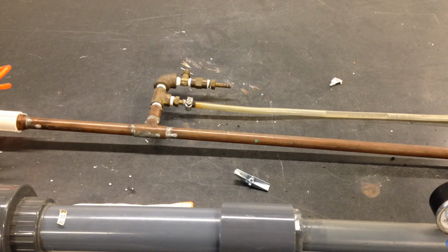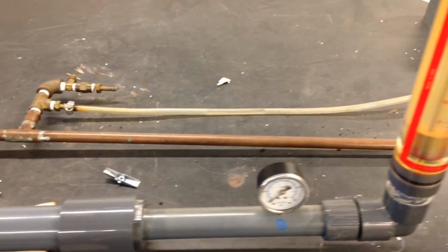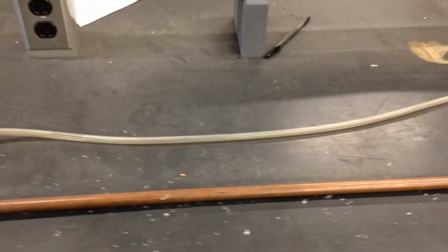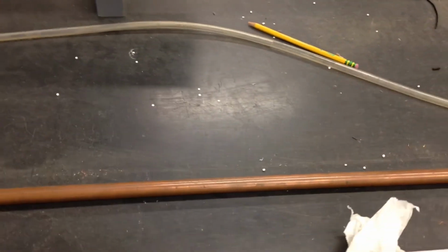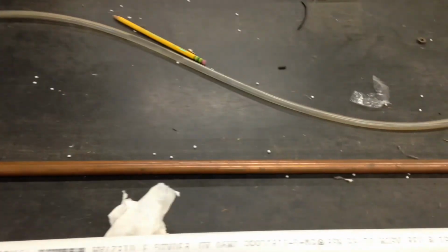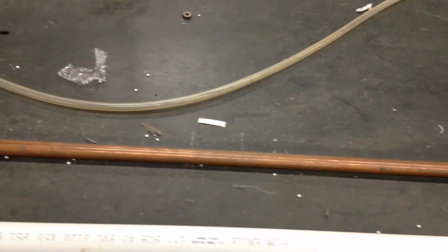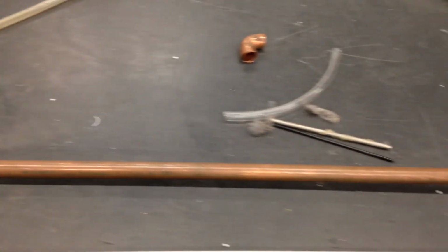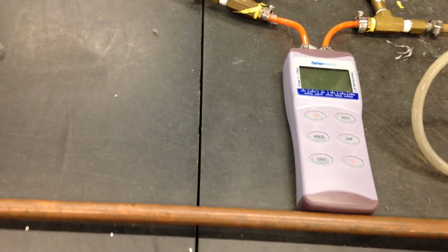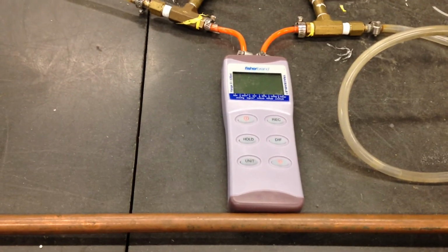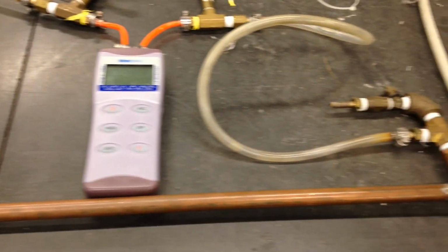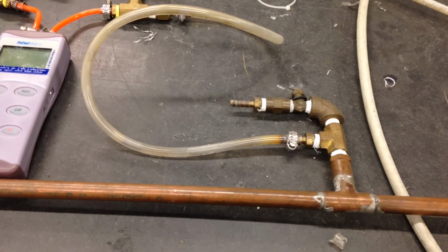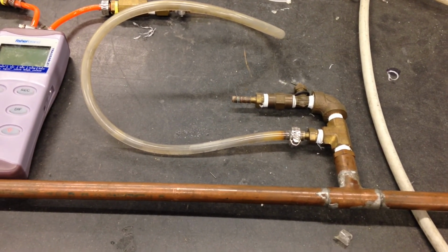The last is a Moody Chart test. We have this piece of copper tubing, that's in the lower part. The upper part, you'll see what it's good for in a second. And it goes along across the breadth of the flow bench, and it reaches a point where we'll have a digital manometer for that. The digital manometer will record the head loss, again in inches of water, from one end of this to the other, or at least between the two taps. And all the dimensions will be given to you.